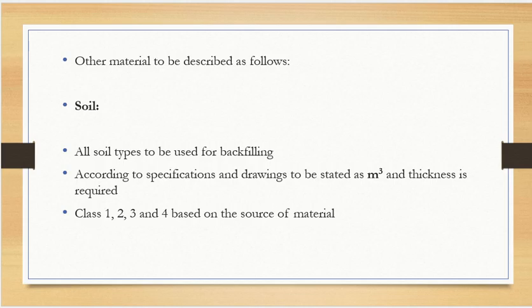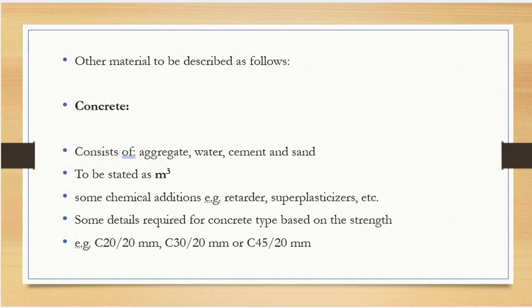The other one is filling, which is what you see for roads maybe. This is my ground level, this is my road level. I will not do any excavation. I fill. This is filling. Earth fill, sand fill, whatever. So there is a difference between them. These classes are mentioned, and you have to refer to NRM, New Rules of Measurement Standards, for these classes.